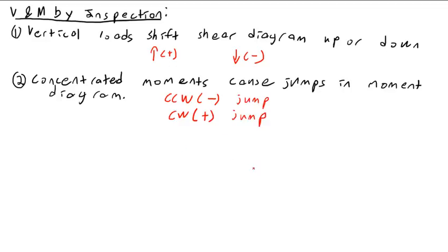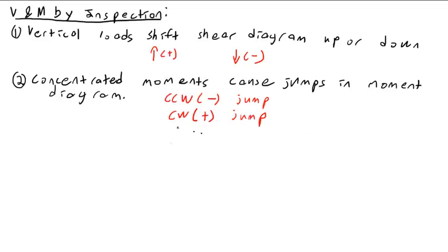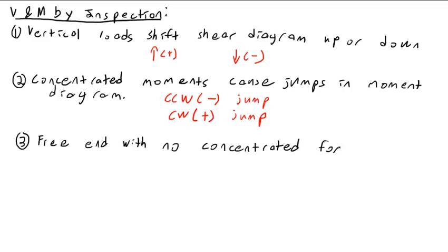Some other principles. So basically this is built upon 4 principles. Three, a free end with no concentrated force or moment: V is 0 and M is 0.